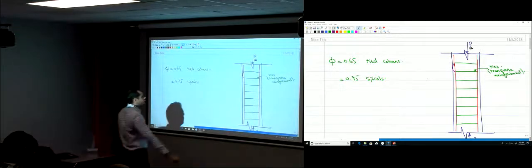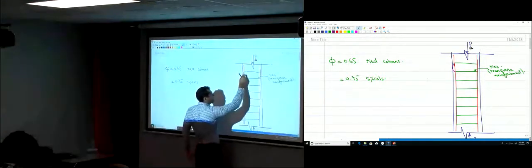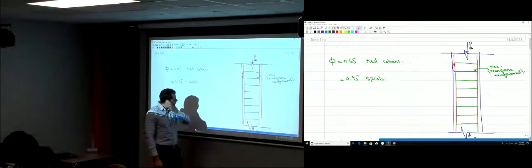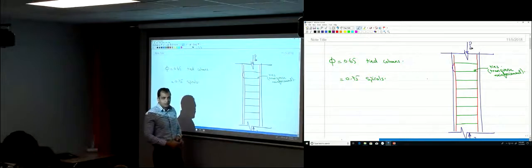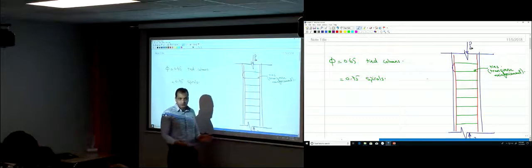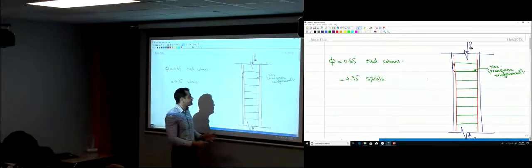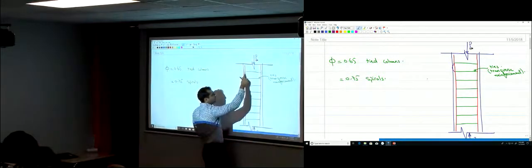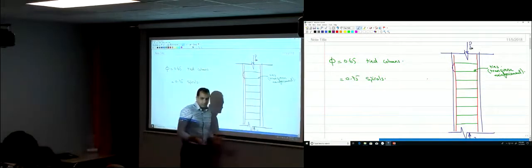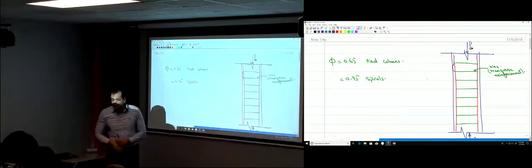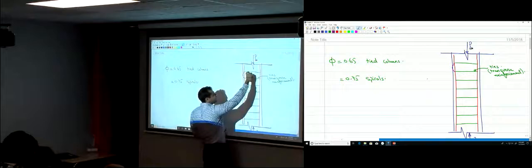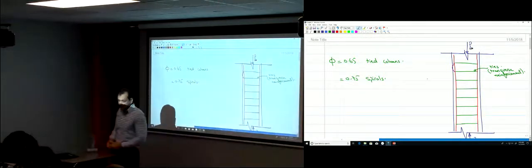Those longitudinal bars buckle. They are under compression. Those are very slender bars, okay? The cover here that was supporting them will actually collapse. That's good because it's not confined, so it's going to collapse first, and that will leave those longitudinal bars unsupported, so they will just buckle like this, and then failure will happen, okay? To make sure that buckling is restrained to a certain limit, this spacing between the ties is limited, okay?